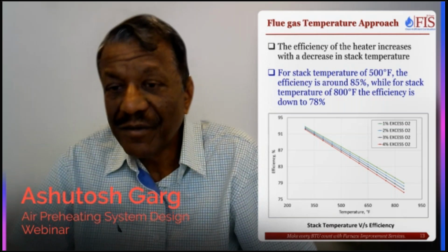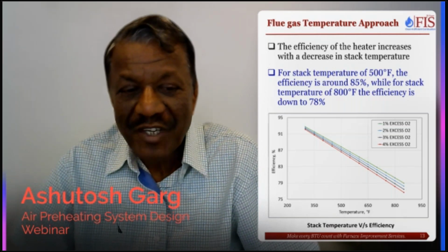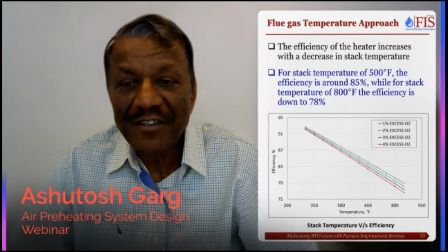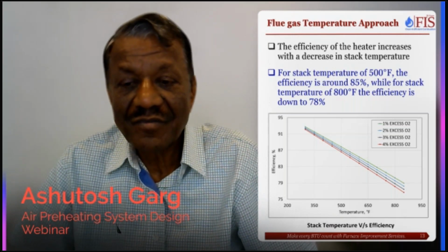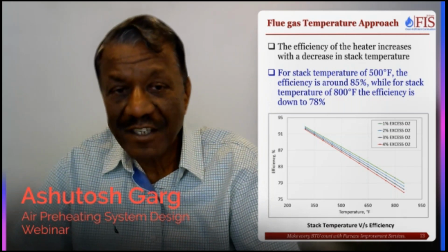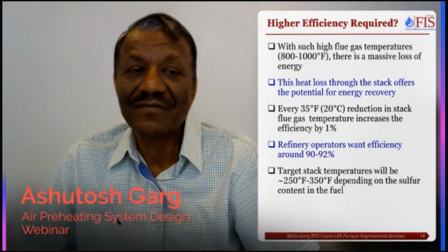That's a separate webinar I will do about controlling the excess O2. But the bottom line is, if you want to maximize the efficiency, we have to reduce the stack temperature as much as possible.